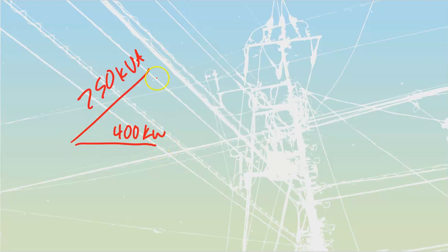They go into Pythagoras, solve for that third side, and then from that third side, they go back using cosine or tangent or inverse cosine. I can't remember. They use the inverse cosine to solve back to that. What I'm recognizing over here, though, is that I've got watts over top of VA, which is equal to my power factor. So that equals my power factor. I can once again punch this thing in all as one thing, to get to the same values.